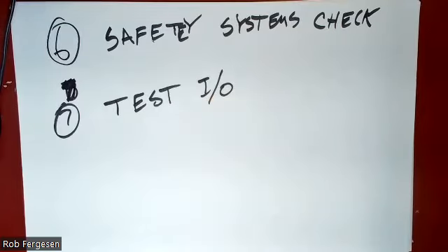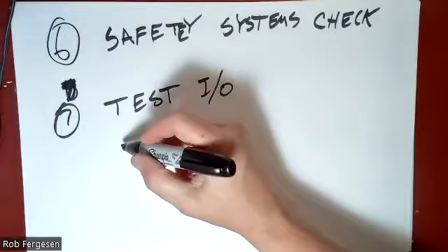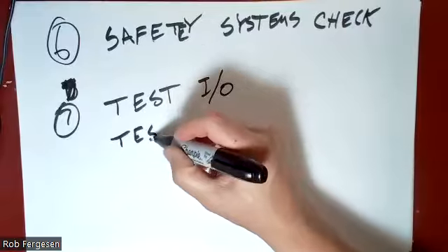For instance, in our robot systems, we know we wired up that I/O, but we can also go before we run that robot program and turn on the outputs and make sure the thing it's wired up to shows that it's turned on somewhere. All right, so you want to test your I/O, and you want to test your inputs. So you might have a sensor turn on. I want to see that that sensor triggers an input to the PLC or to the robot. So we want to test our I/O. And then we're going to test the modules.